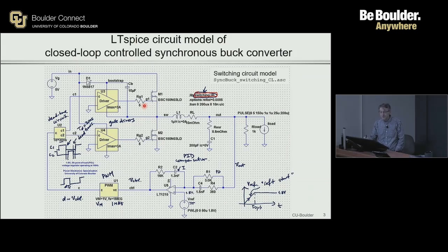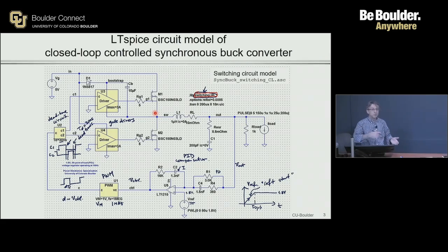When you look at the transient waveforms of what these devices M1 and M2 are capable of doing and how fast transitions we observe at this switching node, you will see that those would be in the order of maybe 20 nanoseconds or so. Now that does not mean that's always going to be the case. If you look at a 400 volt type switching with very different devices and much longer transition times, you may want to have dead times in the order of a few hundred nanoseconds, right? So it is very much application detailed circuit design oriented.